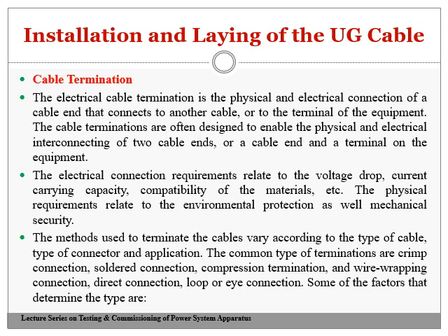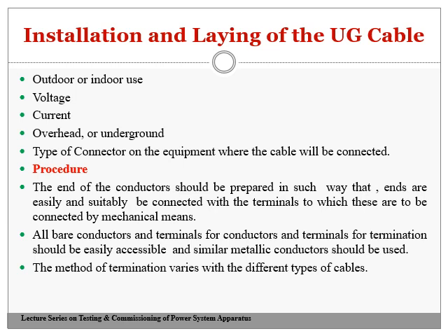Some of the other factors that determine the types are: outdoor or indoor, that is where you're going to install it, voltage, current, whether it's overhead or underground, and the type of connector on the equipment where the cable will be connected.